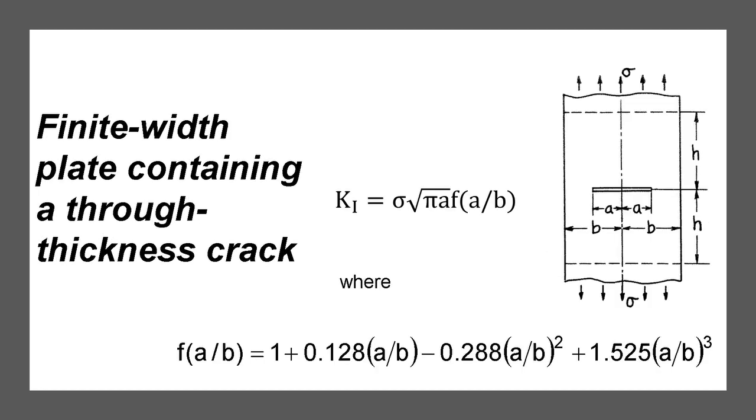The solutions of the stress intensity factors have been obtained for a wide variety of problems. For a finite width plate containing a through thickness crack, the equation developed for the infinite width plate is multiplied by a factor, which is a function of both the crack size and the width of the plate.